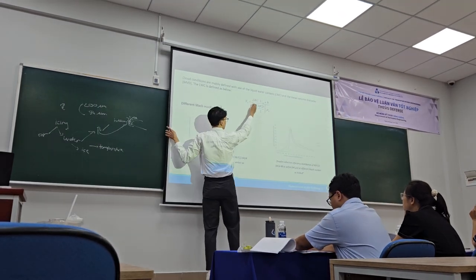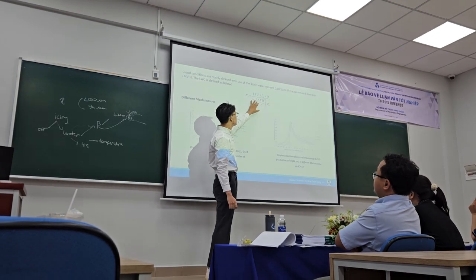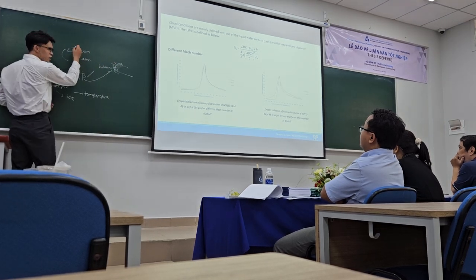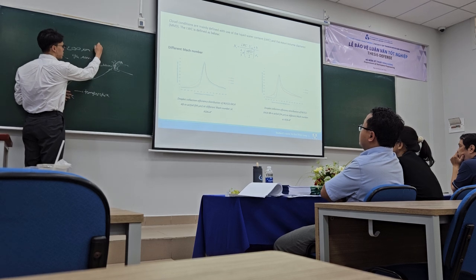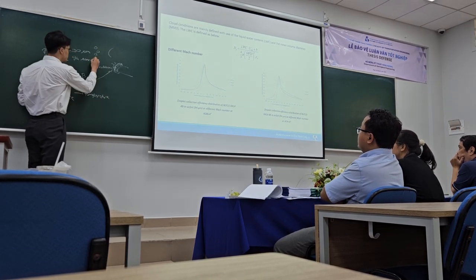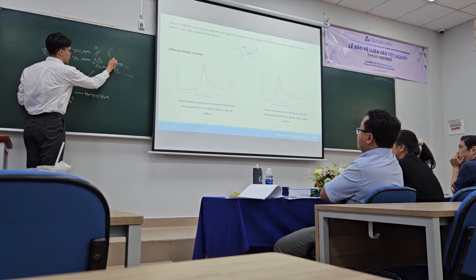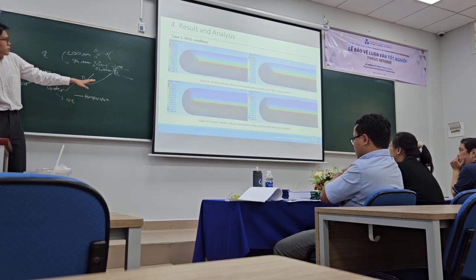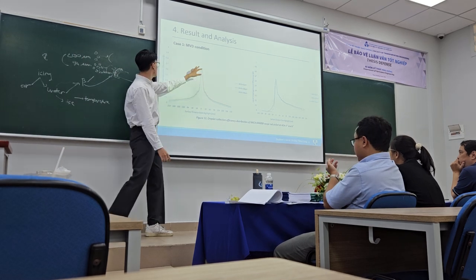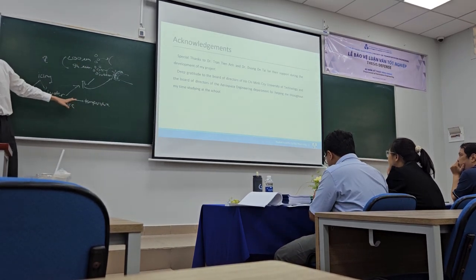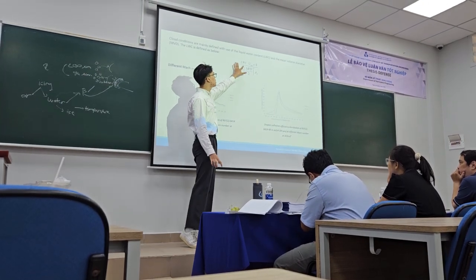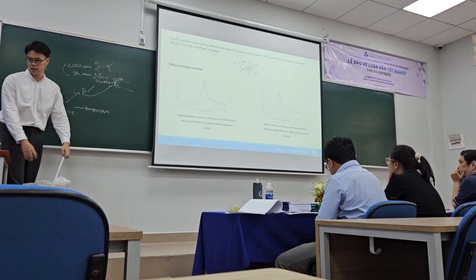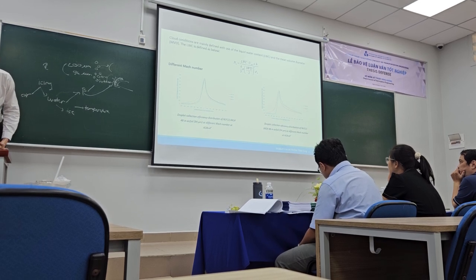If all the other constants are held, with the increase of MVD, it is negatively related to the number of droplets. That means with larger droplets, fewer droplets collide with the airfoil compared to small droplets. With small droplets, we will have more droplets in the air colliding with the airfoil. So this causes the balance, and the difference is not significant. It's just small because of the formula. These two parameters are not the same. It's not that both increase. It's in contrast.